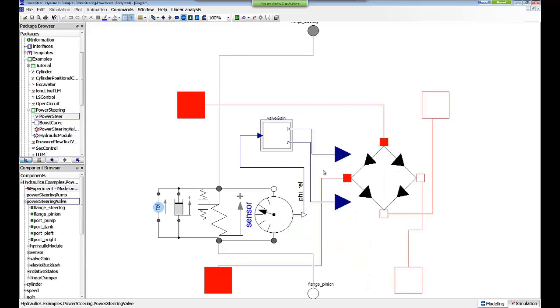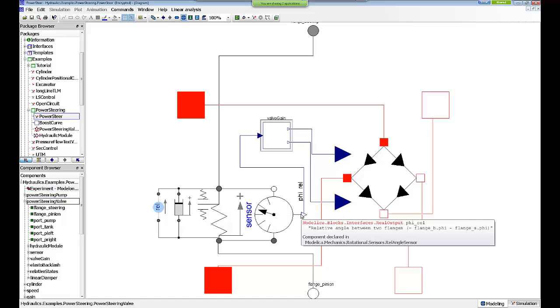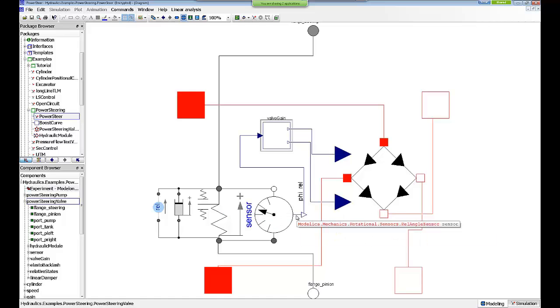So this is the steering input, and this is going down into the pinion. And in between these two here, we have a mechanical spring with an elastic backlash. So basically we can start turning the wheel, and we will deform this torsional spring. Now the deformation here in the spring is an output to the booster. So we know how much lagging we are getting with the relative angle between the rack and the steering input.